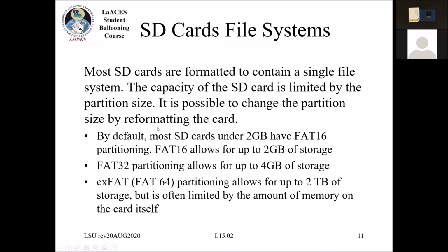But the key takeaway here to remember is this 2 gigabyte limit on the FAT16 file system, because at least on the library we're going to initially work with, it's going to assume FAT16, which means even though our SD card may be 64 gigs or 128 gigs, the software will only be able to deal with 2 gigs of that space.